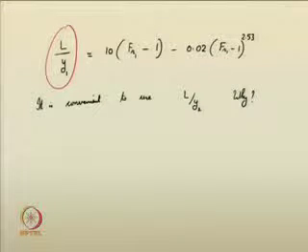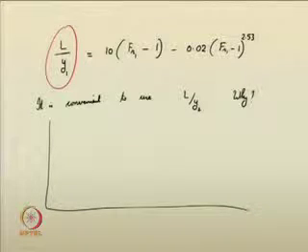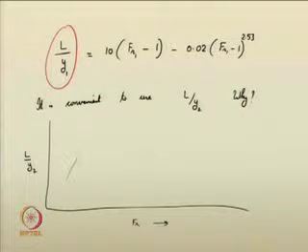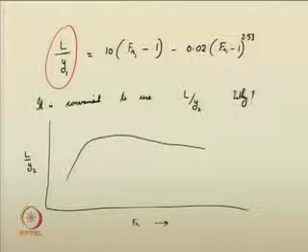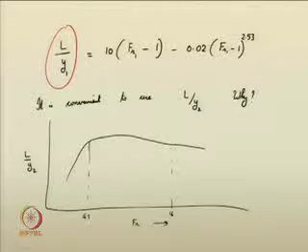One of the reasons is that when they plotted the upstream Froude number with respect to the ratio L by y2, they found that the curve is more or less uniform for a certain region, say from Froude number 4 or 4.5 to 16, roughly having the same magnitude. The ratio L by y2 is almost in the same range, it is not fluctuating. For example, with L by y1 when you plot it, you may not get the relationship in this form. So, convenient for design purposes, people have started using the L by y2 ratio with respect to Froude number for evaluating the length of the jump.